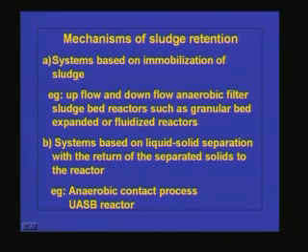In these cases, some inert material is there, either sand or plastic media or any synthetic media, on which the biomass will be growing. Naturally the medium will have high density, so it will not go out of the system along with the liquid. Whatever biomass is generated in the system will stay inside the system. So definitely we will be increasing the biomass concentration.